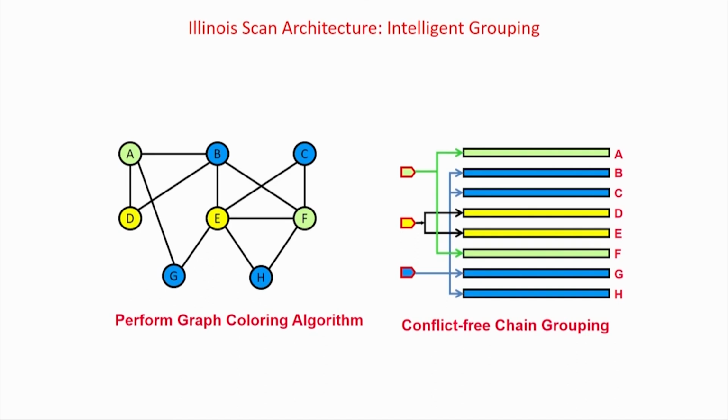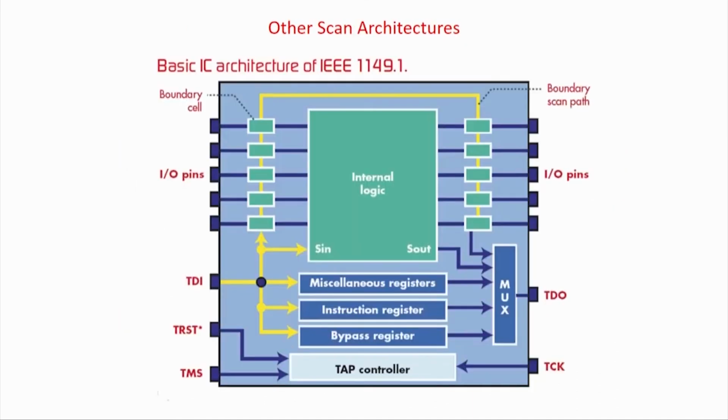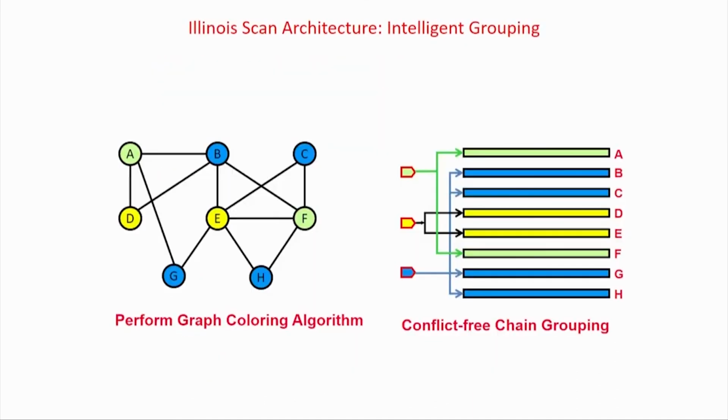So the problem is very simple to design, very simple to map, but solving will take a long time because in such big circuits the graph itself will be large. So we will follow different types of heuristics to solve the problem. Now, this is about your flip-flops, scan chains, partial scan, and of course with the Illinois scan architecture you can also embed partial scan to make the problem more interesting and more practical.